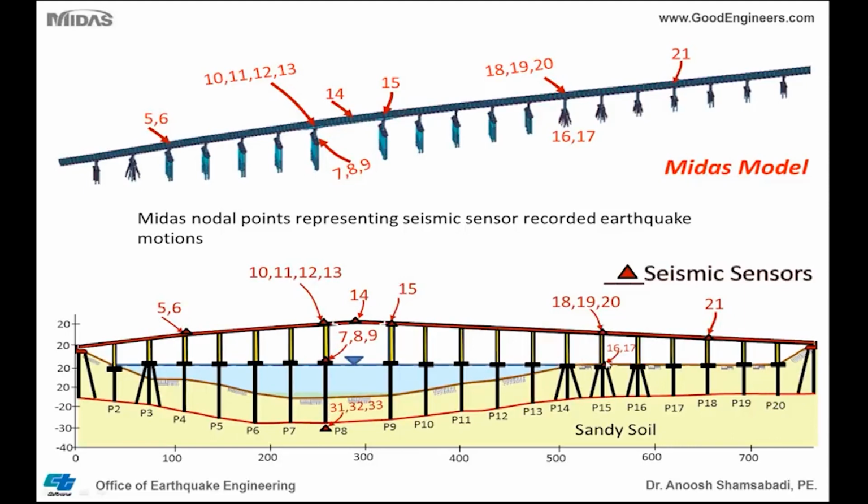Now, as an engineer, before you do any analysis, you need to step back, look at the schematic of the bridge and see what you really should expect from your analysis, what you think you're going to get that makes sense when you run the analysis. If I look at the schematic of this diagram here, you can see some of the pile caps are buried into the soil. Starting at pier number 14, the piles are cantilevered above the mud line and support a massive pile cap. So when I do my analysis, any action that I should see is really in this zone, because most of this is very stiff, but here is where I have the cantilever and the massive structure, and all the actions should be happening in this zone.